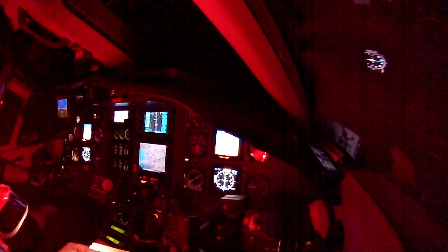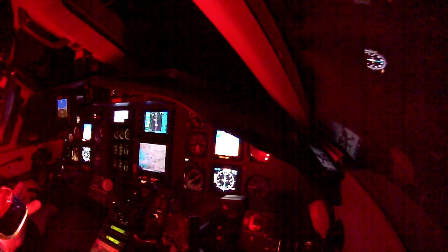That's almost like an ILS approach. ILS is usually 200 feet above touchdown zone elevation and half a mile. This is giving you vertical guidance. It's much more precise with WAAS. So if you're doing a lot of GPS approaches and flying into a lot of remote airports that do not have ILS approach or equipment for an ILS approach, and all they have is GPS approach, a Garmin GPS WAAS is much more beneficial for you if you're flying hardcore IFR instruments. Somebody else asked about going into small airports with GPS.